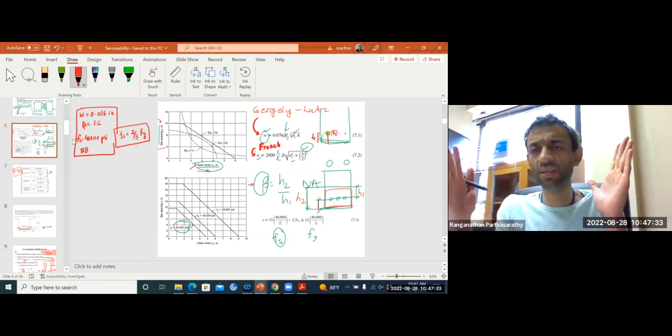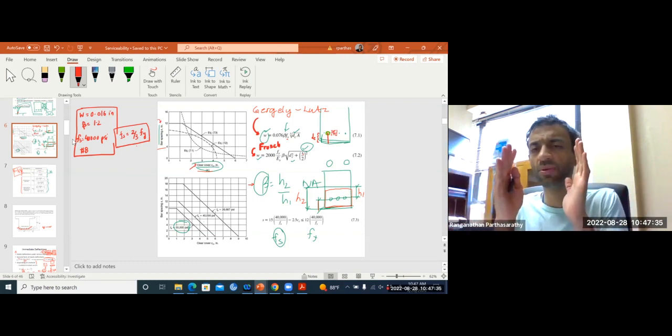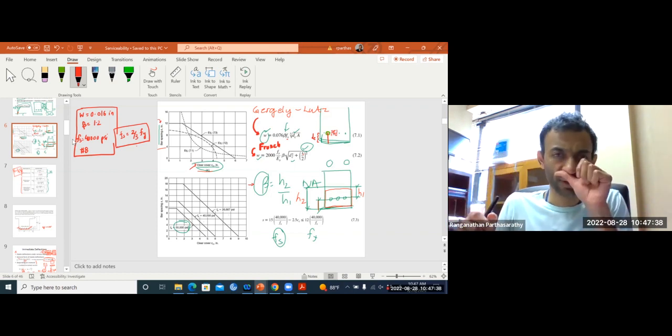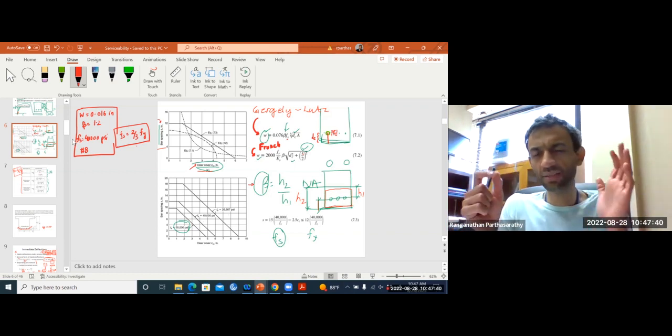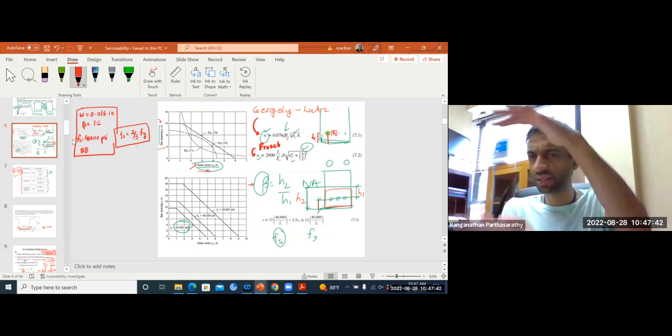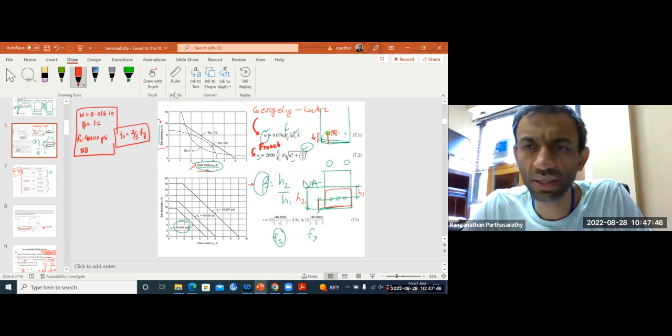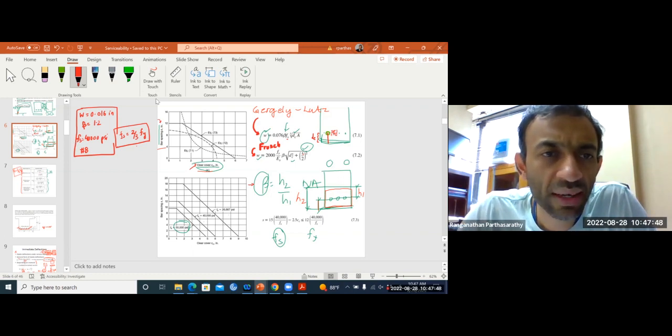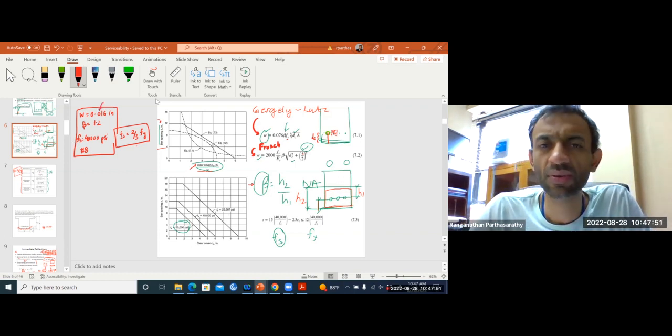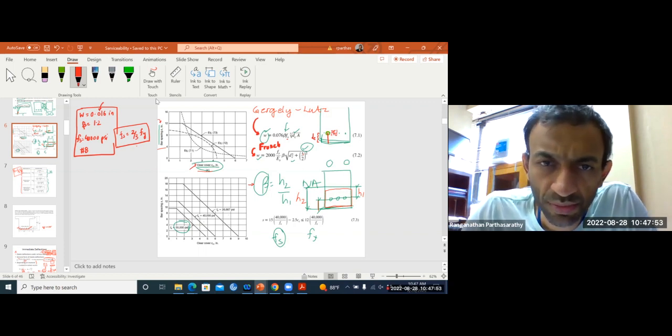To compensate for that, your bar should be spaced more closely. Conversely, if your bars are spaced wide apart, you cannot put too much clear cover. So there is a balance between these two things in order to maintain your crack width below this value. So how does equation 7.1 look?